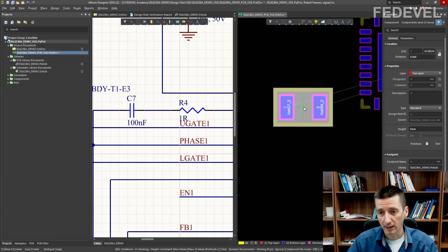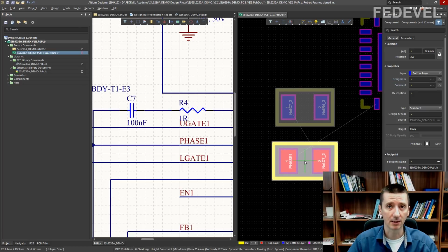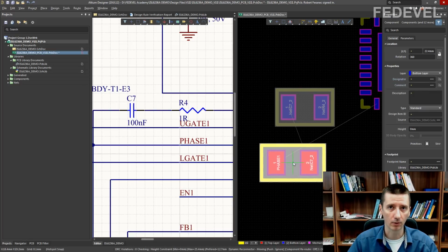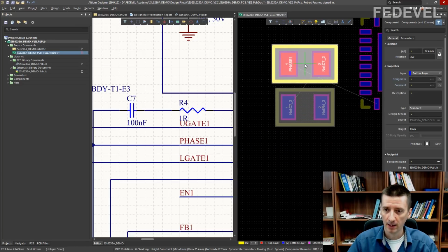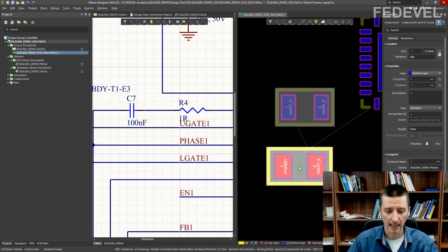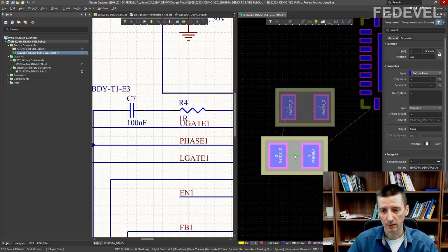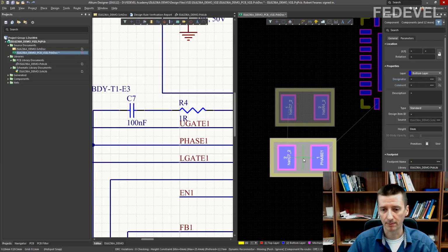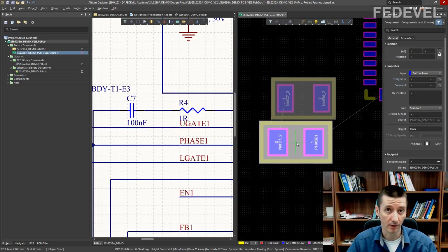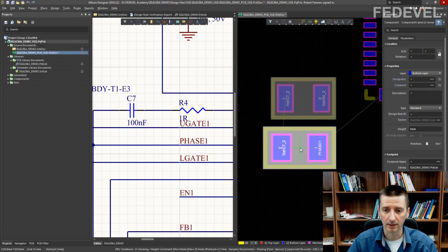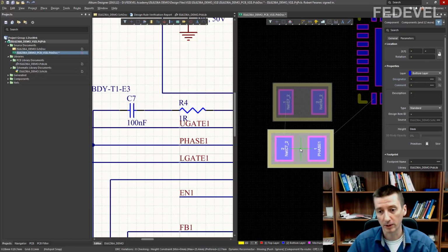To place the component, simply just press left click, and now we are automatically holding the second component what we selected, the capacitor. We would like to place it on the bottom side, so press L, and we don't have to rotate this capacitor because based on the connections, it looks like it will be easy to connect the capacitor with the resistor and with the chip, so rotation is perfect.